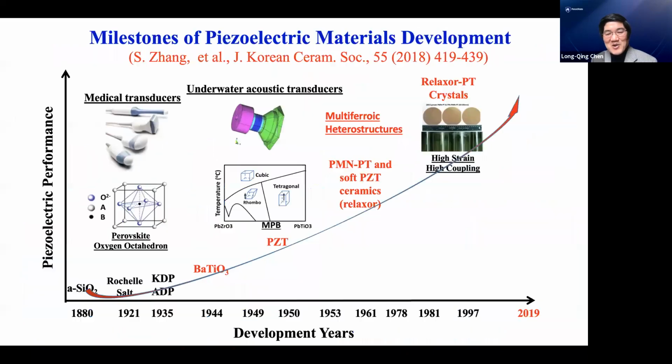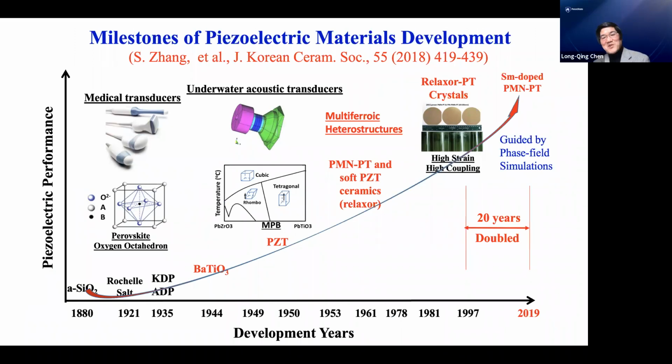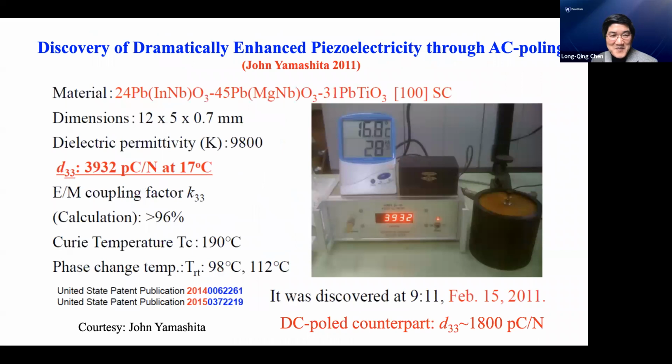So this milestone, due to the guidance of our simulation, we discovered this samarium-doped PMN-PT crystal, with almost double the piezoelectric response of the crystals from about 20 years ago. We were pretty happy in this case that simulations were able to provide the guidance.